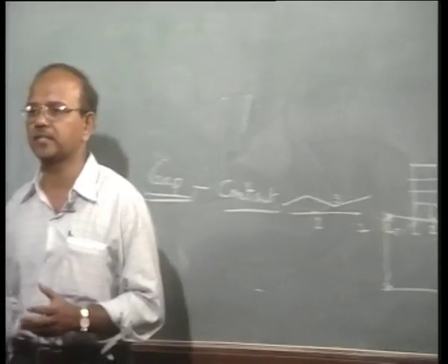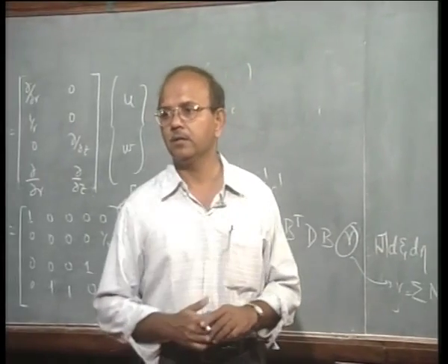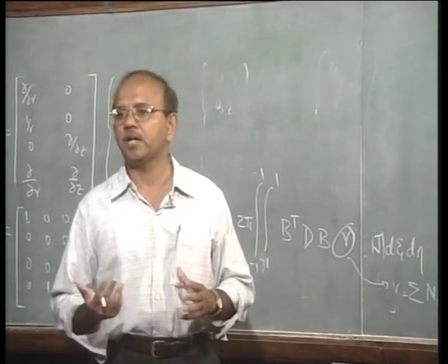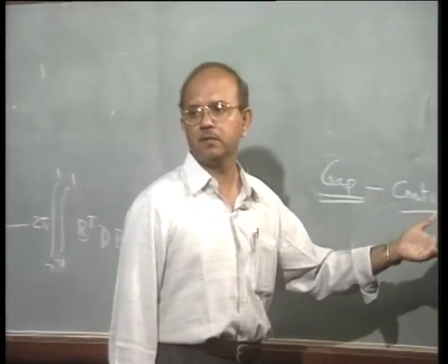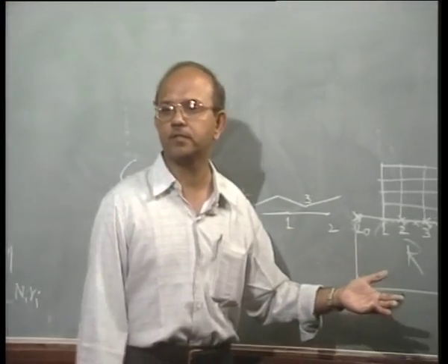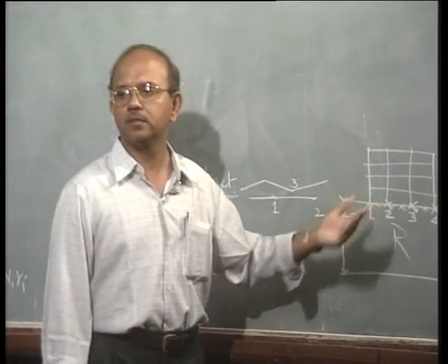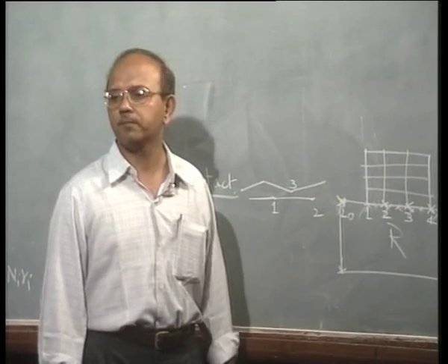Suppose you are working with a package like ANSYS, the package will ask you to pick up 2 surfaces, a target surface, one that it will call the master surface, and another that it will call the slave surface.